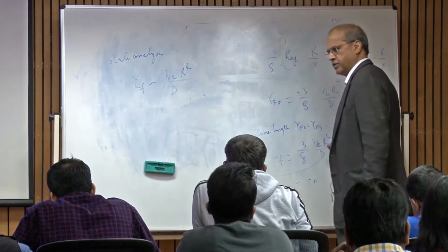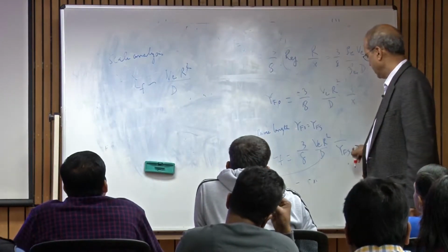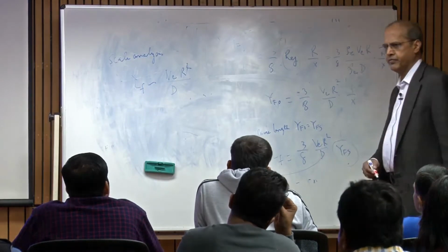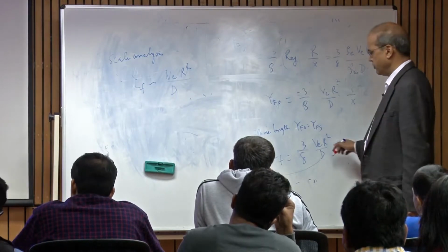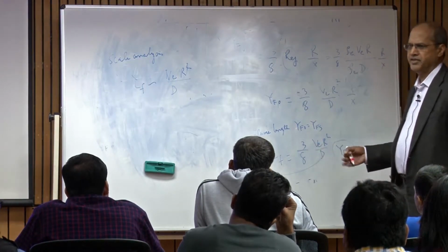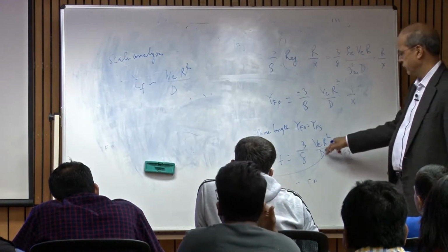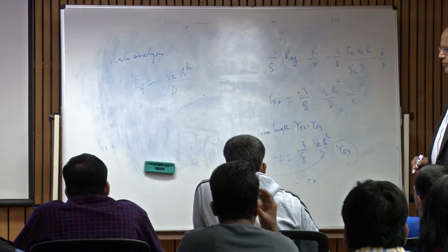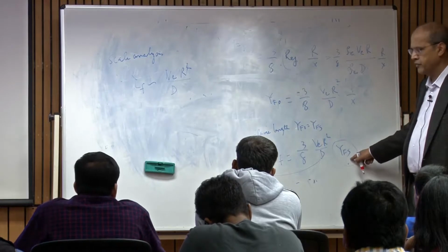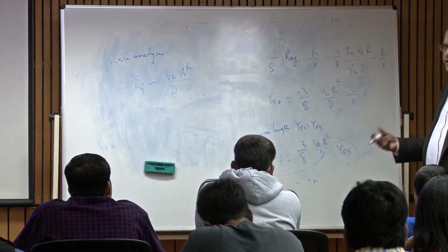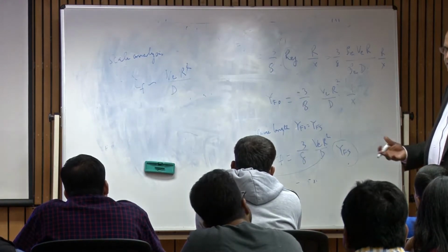So those three parameters are here also, V, r square, d. In addition, now we get the fuel dependence. Of course, this again gives you a qualitative picture. It won't give you exact values of LF, but it gives the correct variation with these four parameters. So this also gives you the variation with fuel-air ratio. For different fuels, YF value is different.